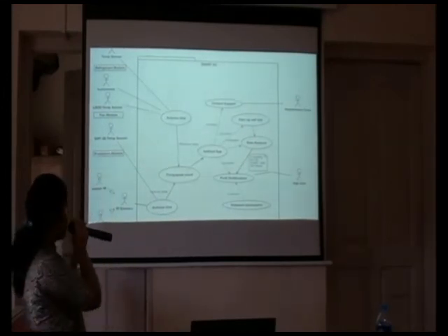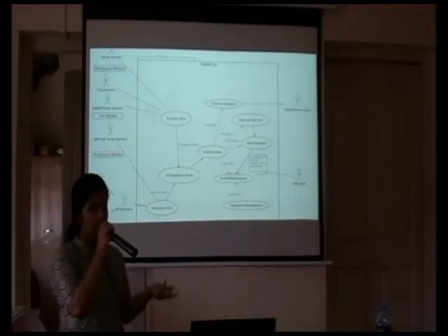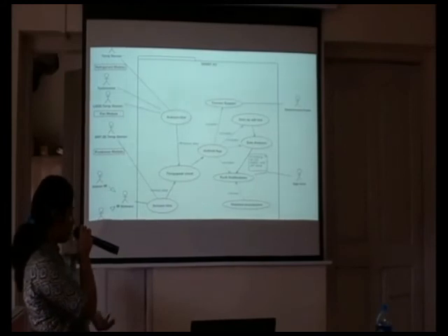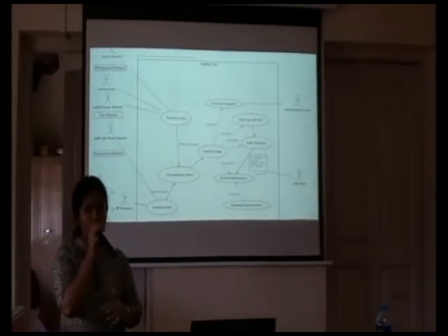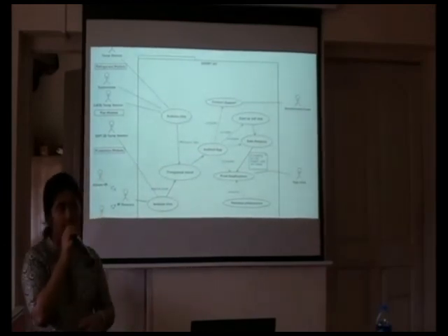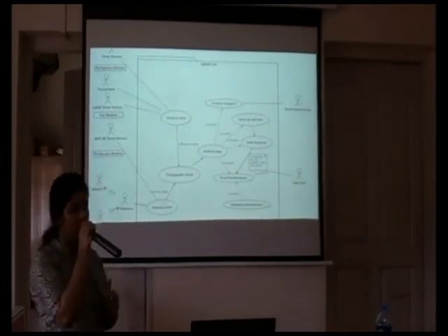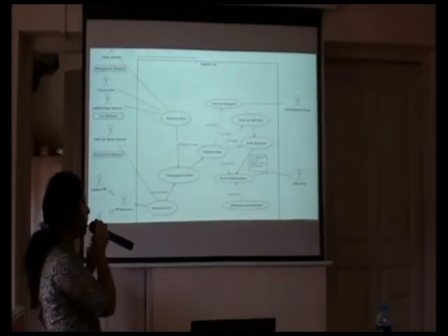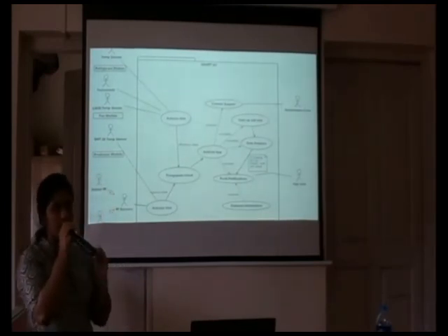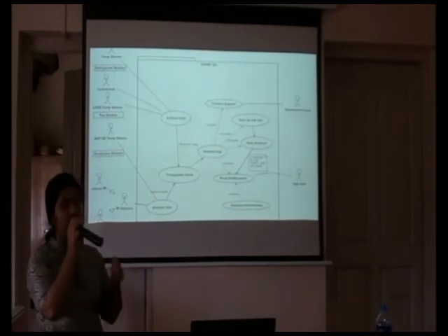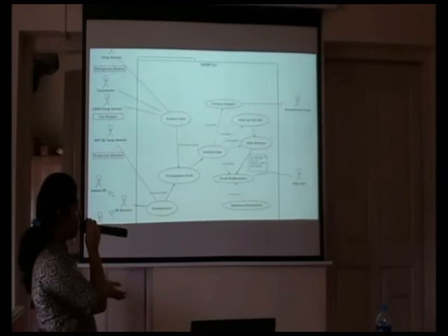The data from the IR sensors placed on the indoor filter as well as the outdoor filter are being sent to an Arduino UNO board. The Arduino UNO board collects the sensor data and uploads it to a ThingSpeak Cloud via a Wi-Fi module. The ThingSpeak Cloud stores the sensor data, and this data is being retrieved by the Android app. The Android app serves several purposes.